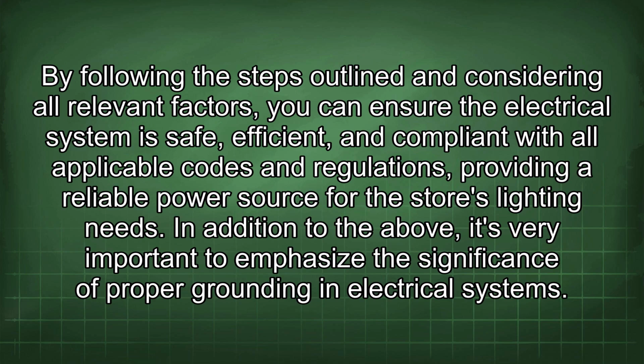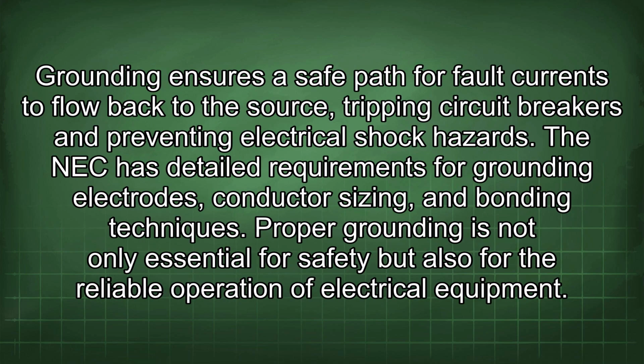In addition to the above, it's very important to emphasize the significance of proper grounding in electrical systems. Grounding ensures a safe path for fault currents to flow back to the source, tripping circuit breakers and preventing electrical shock hazards. The NEC has detailed requirements for grounding electrodes, conductor sizing, and bonding techniques. Proper grounding is not only essential for safety, but also for the reliable operation of electrical equipment.